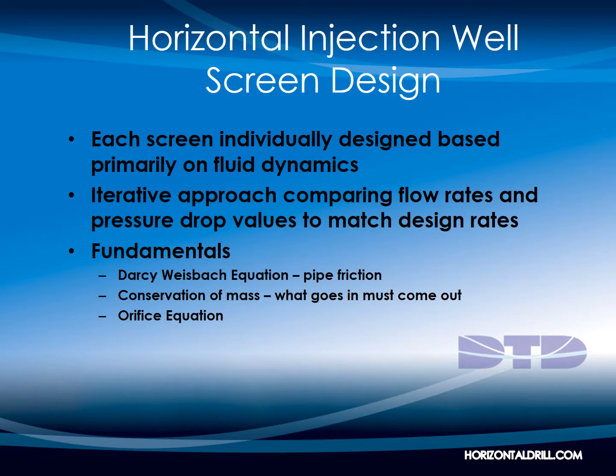We then take all the details and use math. That's right, this isn't some sort of voodoo or black magic. We use standard fluid dynamic equations to design a screen that delivers the injectate evenly across the screen based on all the project parameters. Think I'm crazy and it still can't work? Let's have a visual.